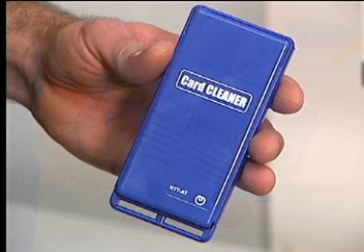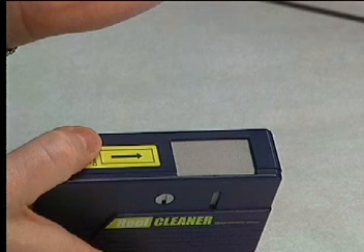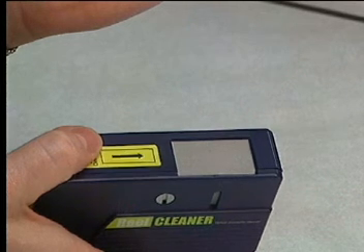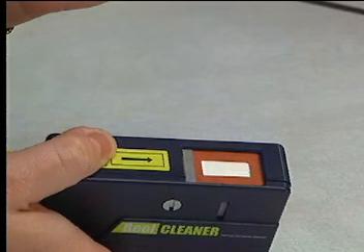Most are used dry to avoid attracting airborne contaminants. Among the most popular are the dry tape-based cleaning cassettes. To use this type of cleaner, the tape is first advanced to expose a fresh, unused section. A small flap protects the tape from airborne contamination until the instant the technician is ready to use the tape.